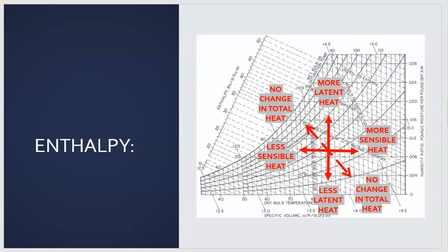Then you have the two oddballs, where there's a trade-off. If you both raise the temperature but lower the humidity, you're more comfortable in the space, but you haven't actually changed the heat load in the space. The same thing if you bring the temperature up and then dehumidify the space.